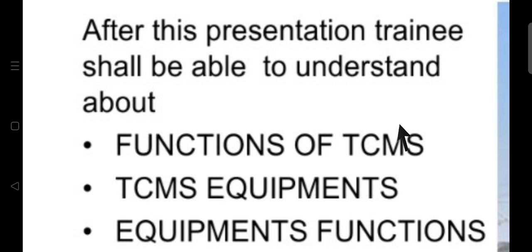What is SIV? SIV stands for static inverter unit, and it is responsible for developing the low voltage supplies, like the 3-phase 415 volt supply, the 220 volt supply, and the 110 volt DC supply. Now what's the requirement of all this supply? Obviously, the 3-phase supplies we use for the compressor and for the condenser of the VAC.